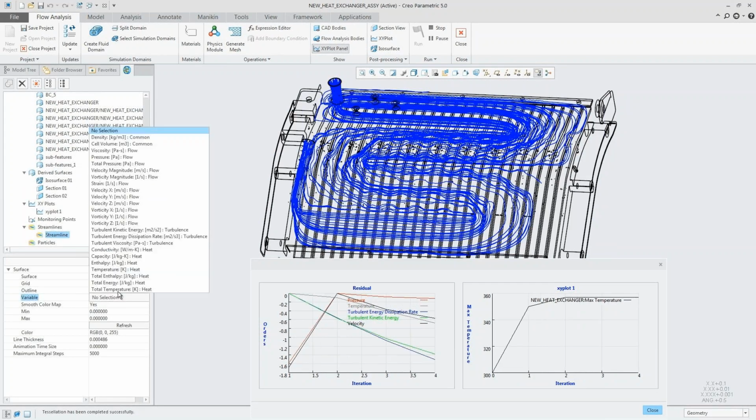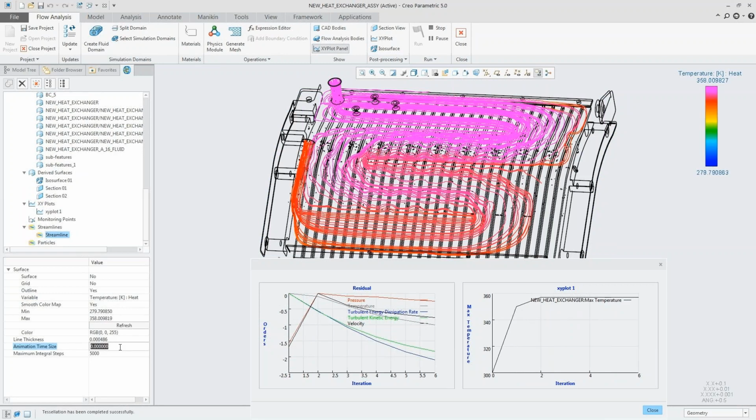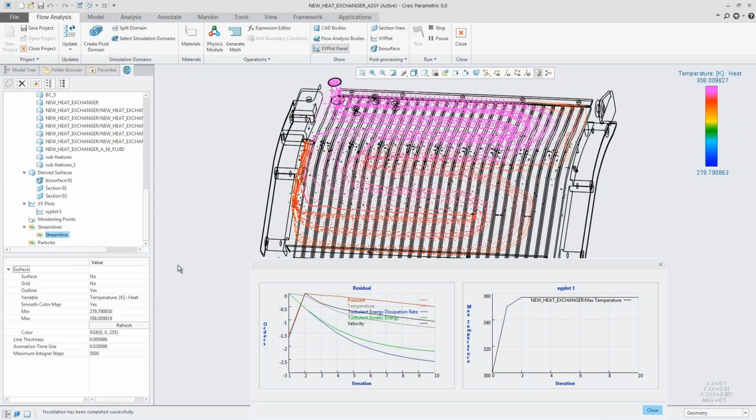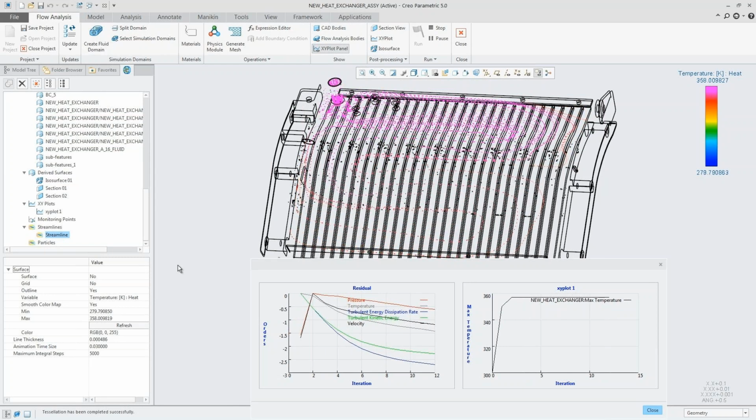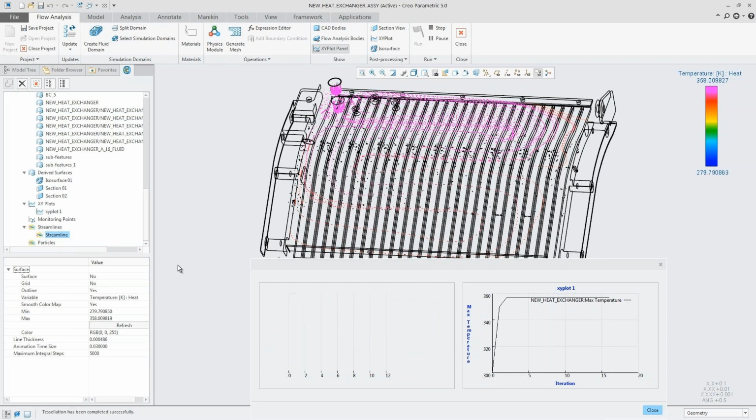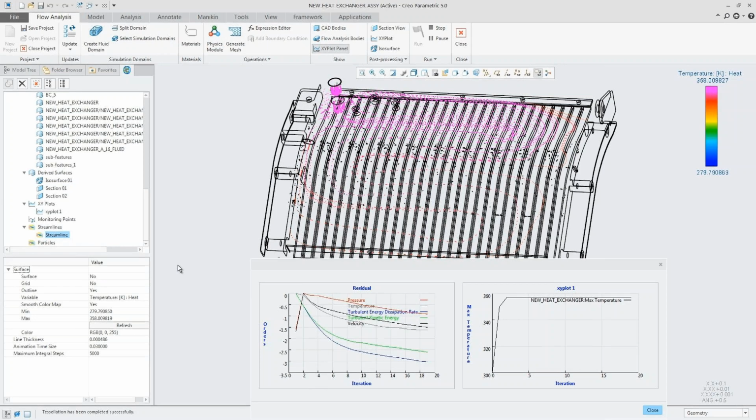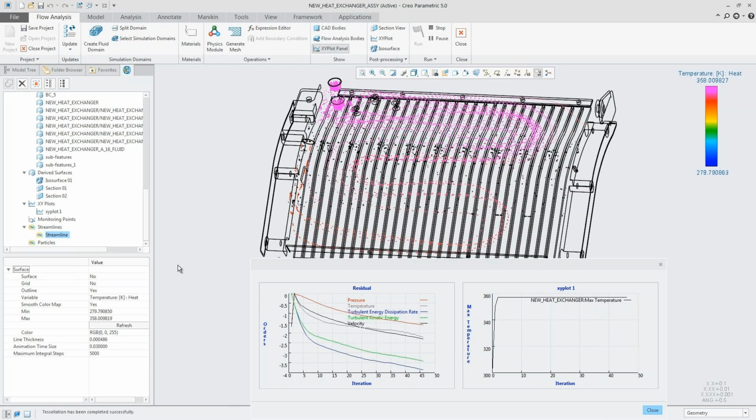And then again, pretty much as soon as we click to run the analysis, we're instantly starting to get back meaningful data. You can see what that's doing, and we can change around any of our properties to get the flow into a form that makes the most sense for us. All right, and so looking at some of our flow information below, we can see that it's starting to go through an update for the more iterations that we go through and run. We're beginning to converge towards more accurate values for things like pressure, temperature, velocity.